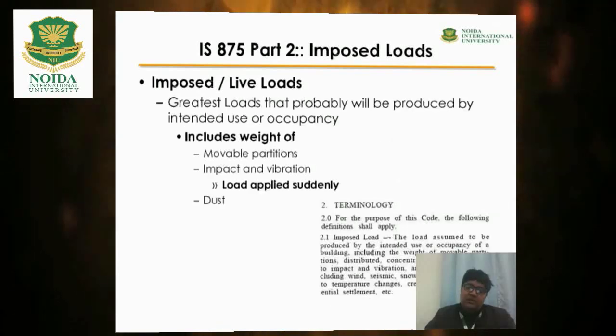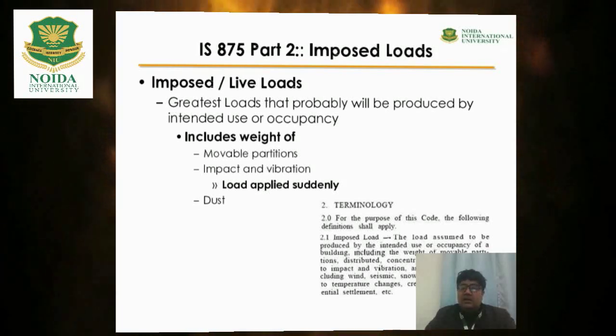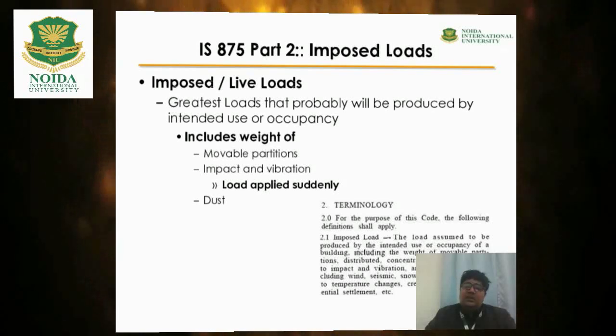Okay, so going further, the imposed load or live load is the greatest load that will probably be produced by the intended use or the occupancy. These are not the dead loads. These are the loads which are applied after the structure is made, and these are the movable loads, movable partitions. If you include the movable partitions, impact and vibrations, load applied suddenly, dust, etc. The sudden load, like a load applied suddenly due to heavy traffic or something else, should be calculated as the imposed load.